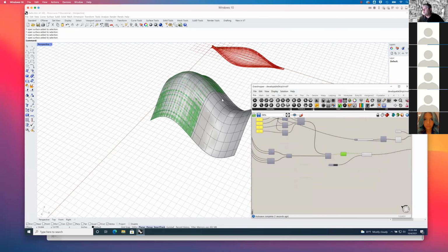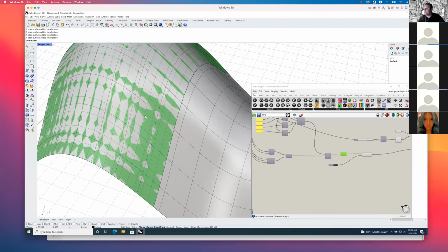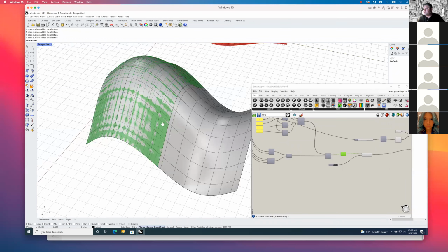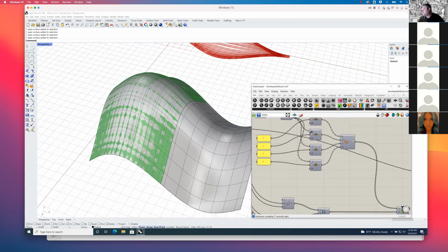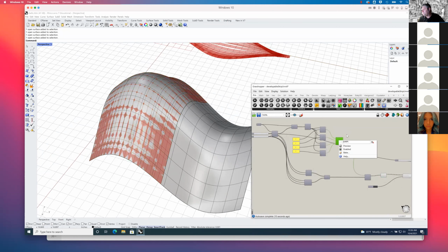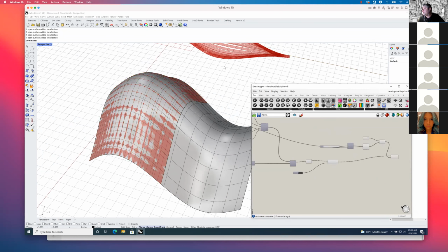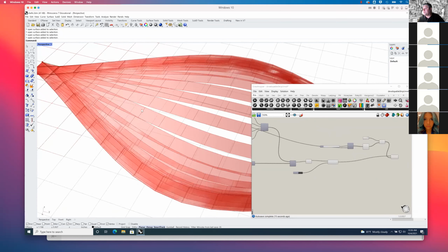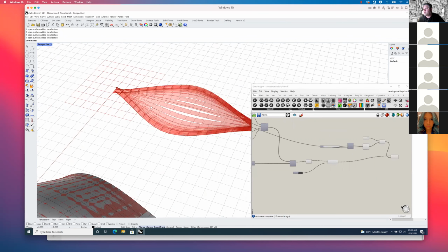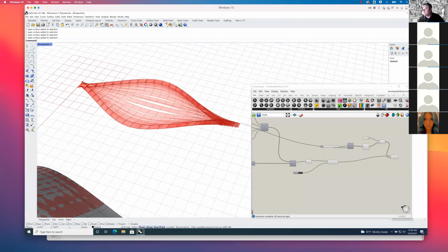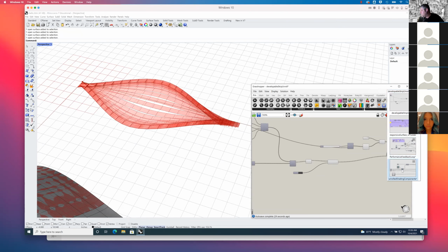All right, so a couple of things in Grasshopper. We'll be taking some of these surfaces, breaking them up into smaller quad-like components, and then unrolling them as strips that can actually be flattened out. You can see that these are all overlaid on top of each other. I need to spread these out. And at the same time, once we develop these cells, we'll be placing three-dimensional shading geometry on them, right? So here's my example.